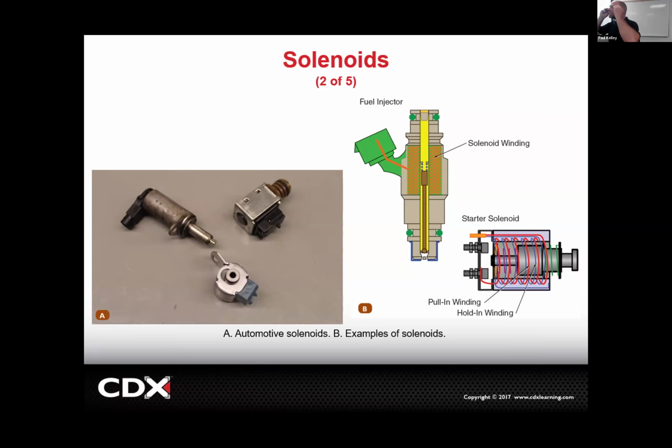So imagine in the most simple form, if you were to have it like this, you could connect this to a switch and you could say, spray, don't spray, spray, don't spray. But we want to pulse injectors so quickly that the ECM is probably going to use a transistor. There's that term again. And the ECM is going to say ground, ground, ground, ground, just pulsing the ground.